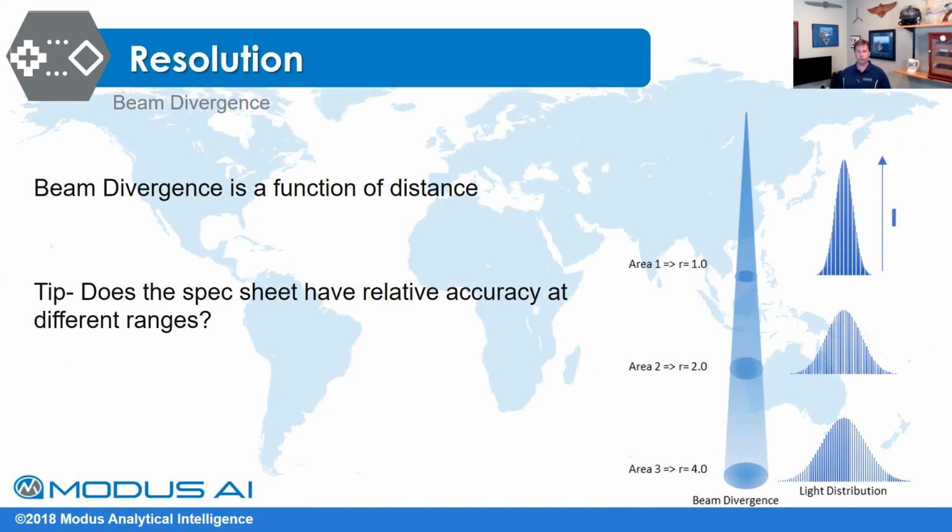And if you look here on your left and right-hand side over here, what we're trying to illustrate here is all light diffuses or diverges. That's why we call it beam divergence. And so the farther away your target is, the larger your spot size is going to be. The reason why we use lasers is it doesn't diverge as much. But when we're dealing with these smaller drone sensors, you're not dealing with the types of optics that you're going to do with like an aviation model. And the heads are going to be a little bit different. There's still some really good heads out there that are going to give you survey grade material, but you just have to be aware that your point density or your point spacing or your spot size is going to change, and that's going to vary what results you're going to get.